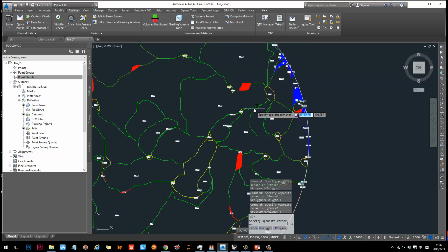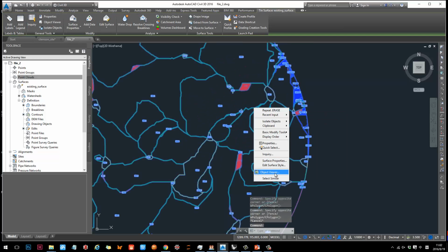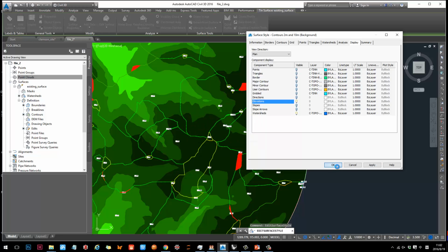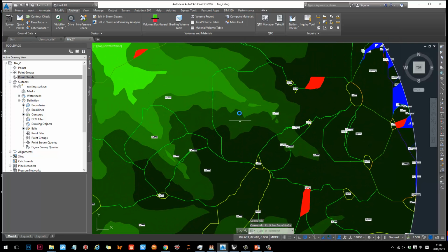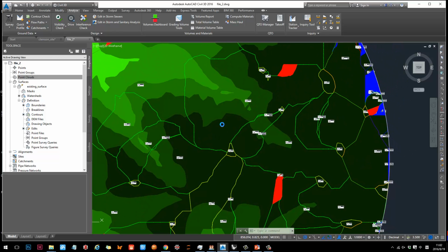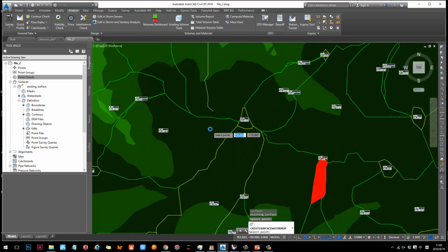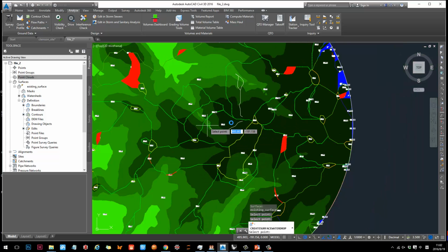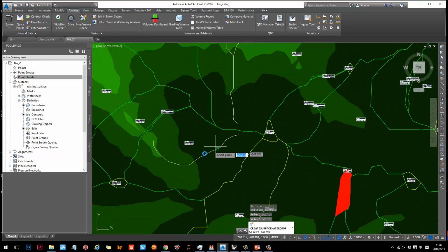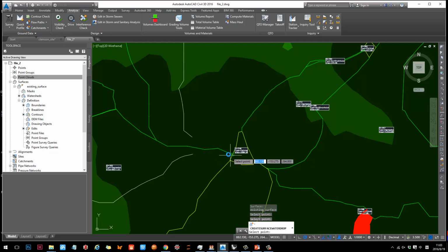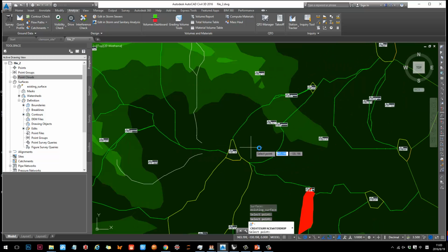If you open up elevation again, then you can understand where the water will go. For example, you go to analyze and then to water drop. If I drop water here, it will go somewhere here. If I drop water here, it will go somewhere else. Even though they are really close, they will flow to totally different places. So that's why these watershed boundaries are important.